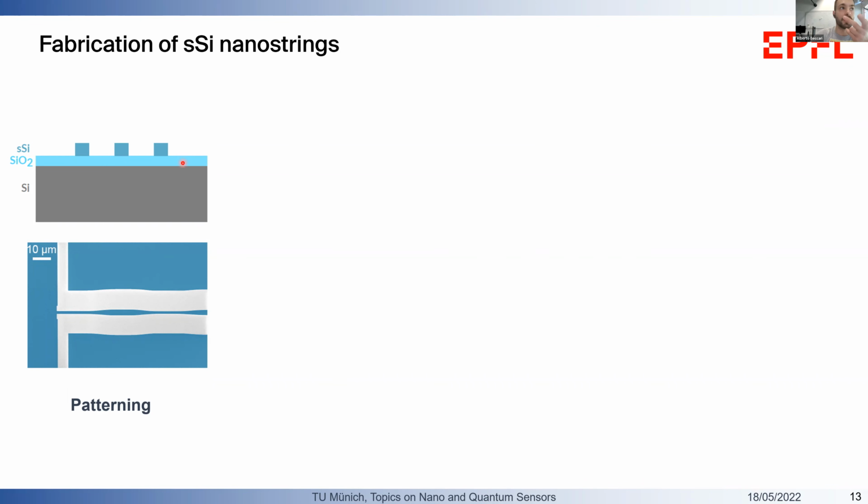It's just 140 nanometers. And if you suspend them by removal of the silicon oxide sacrificial layer, they would instantly collapse on the substrate. Then we had to find a way to excavate the substrate and create a higher recess directly in the silicon substrate, to suspend the strained silicon nanostrings some tens of microns correctly, without stiction or collapse.